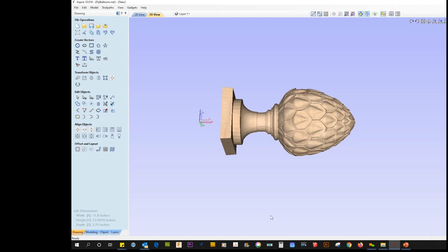You home the machine. The axes are going to turn back to 0. On the Richauto controller, if you press OK, the screen will come up and say, do you want to go back to your work origin? You press OK, it goes back to that work origin. You press run, and no, I'm sorry. You go to the breakpoint and look for that file, and you start it, run, and it will start back again. And it would do that on a power failure.